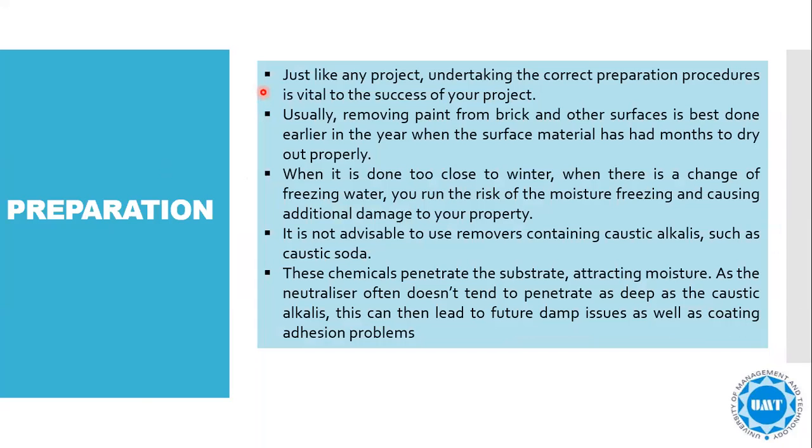With preparation, it's just like any project: undertaking the correct preparation procedure is vital to the success of your project. Usually, removing paint from brick and other surfaces is best done earlier in the year, when the surface material has had months to dry out properly. When it's done too close to winter, when there is a chance of freezing water, you run the risk of the moisture freezing and causing additional damage to your property.